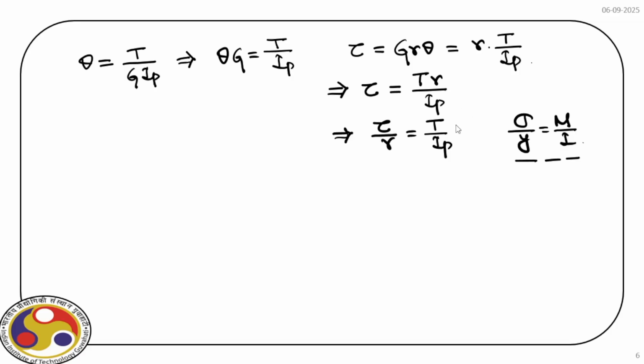As we move away from the center, the value of shear stress is more and it varies linearly from the center. Right. Now just imagine if we have not a solid circular cross section but a hollow one, and say the inner radius is R1 and the outer radius say R2.